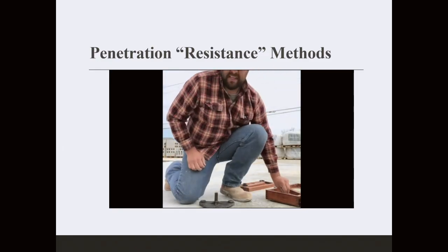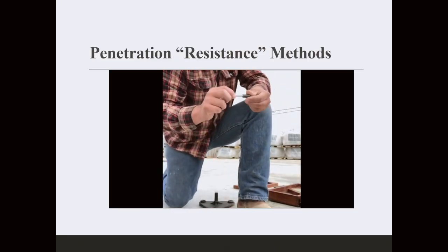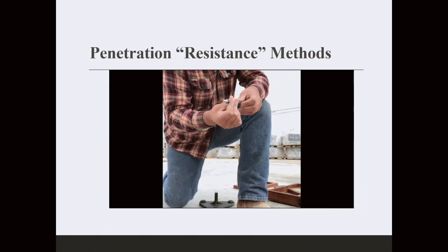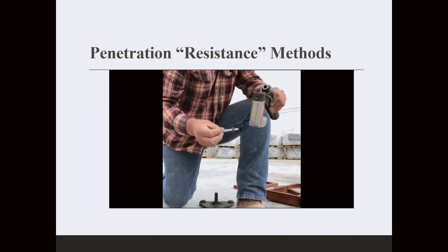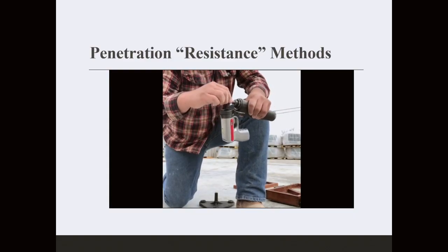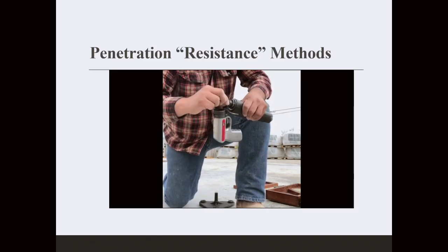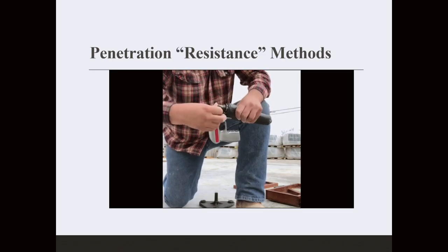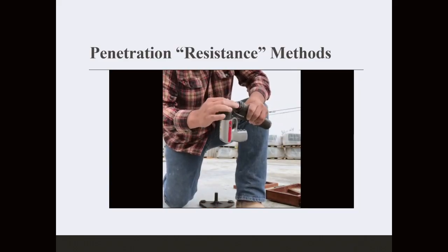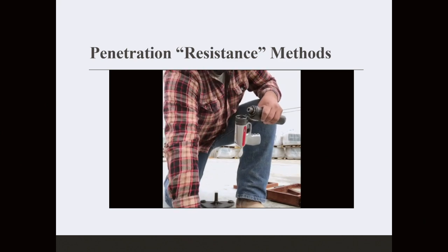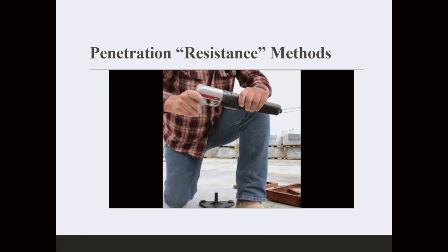I'm gonna grab this little piece out of the box, and I'm gonna screw this onto the tip of the probe as far as it goes. Obviously, it won't fit in that way. Well, I guess it will, but it doesn't go in that way. So the tip of the probe that goes into the concrete is gonna go into the barrel first. Shove that in there. This metal piece that came with it, put it back in, push it in as far as it goes, and then slide the bullet into that piece. Turn it sideways, clock it, it's ready to go.